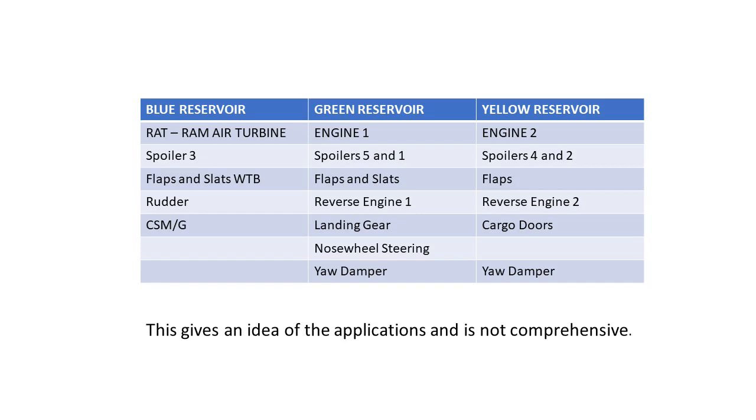Okay, and then also with this we have the pressure relief valve. So besides the check valve, we also have, as part of the green hydraulic system, a pressure relief valve. And what is that? Okay, that's protecting the system from overpressure, right? The two pressure switches and a pressure transducer are also installed on that high pressure manifold so that it can monitor that pressure and not have too much pressure out there.